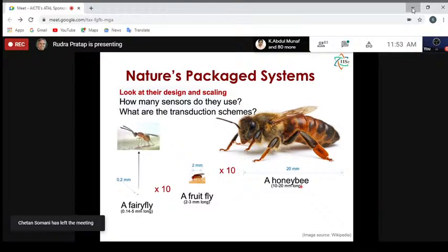Now, if I deposit some other material on top, like polysilicon, it will be going here as well. But before I do that, I remove the oxide layer. You remember that it was like this. Now I can use an etchant which loves the oxide but leaves alone photoresist and silicon. So I can use that and remove the oxide layer. Then I can strip the photoresist.